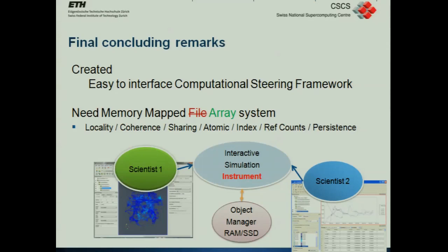In this case, we have a simulation which is running on, I think, 12 or 24 cores. ParaView is running on 4 cores. And we can receive data, we can resample it to a grid, we can isosurface it, we can take meshes like this sphere, for example, generate them in parallel and write them in. The important thing is that we're writing into the DSM in parallel, they're reading in parallel, everything's going on in parallel. It's a proper parallel file system. And all of this GUI stuff over here is generated.